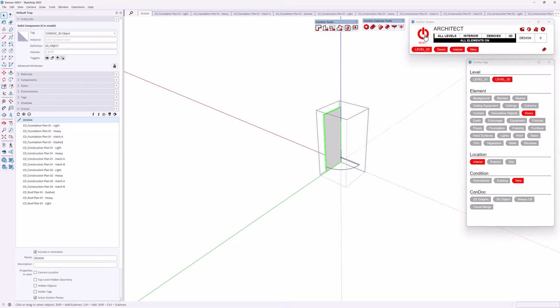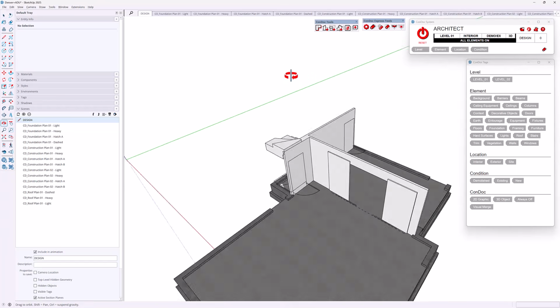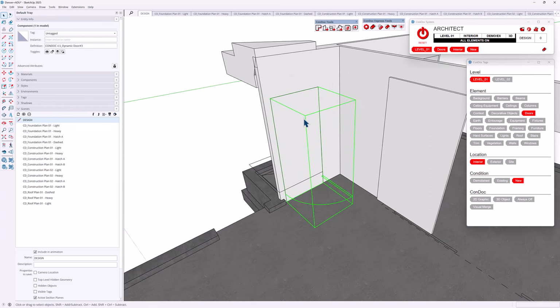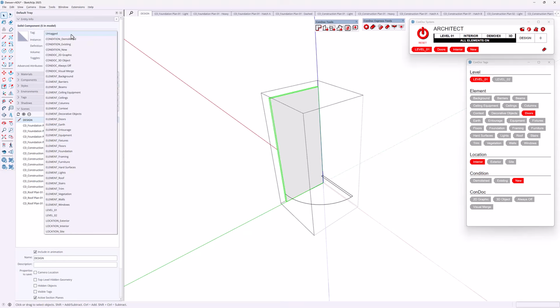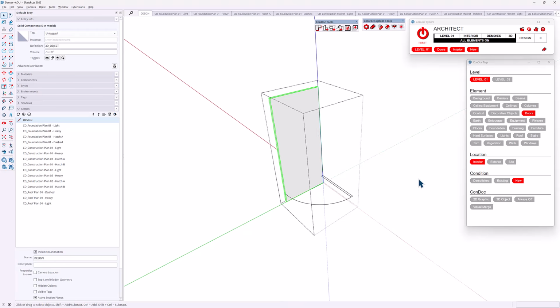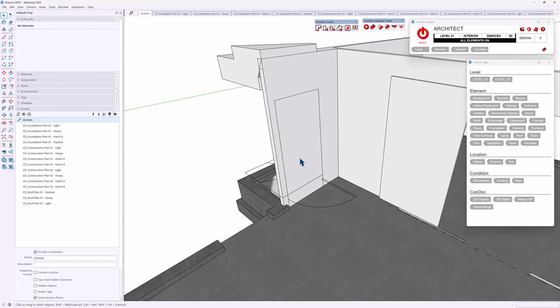Well, if I go back, let me back out of here and go to level 1 interior, and then get back to our door here. All right, and double click in, you can see that this guy, we could use the 3D object. We could do that, or you can just stick with the system and say this is our 3D object and this is our 2D graphic, like that. Now, we should be good to go on that.